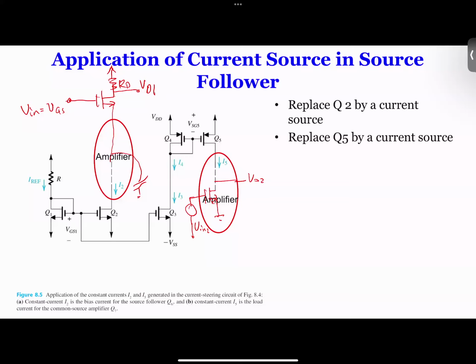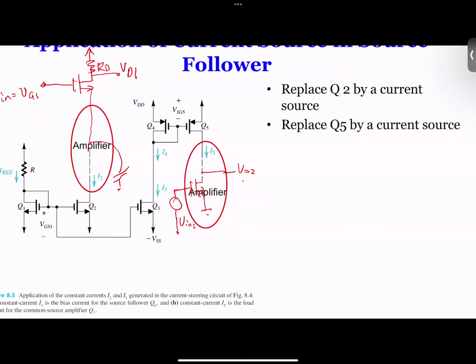This source is grounded. This is a common source amplifier, a very typical common source amplifier. But then you have something at the drain, and this one at the drain is the equivalent, like if we don't have a load here, that's going to be something like an equivalent resistance. Later on, we're going to find out. But if you have a load resistance over here, it will be easy to draw the equivalent circuit.